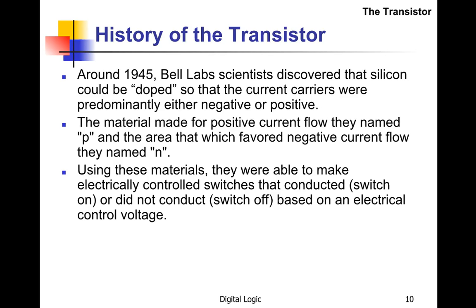And you can do a similar thing with picking the next row over in the periodic table, and that makes it an N-type dopant. And if you put a few impurities of the N-type material into the silicon, it makes it conduct, and it conducts with electrons. So by doing that selectively, you can pick whether the current conductor is negative or positive, and that was kind of the trick for making semiconductor transistors.